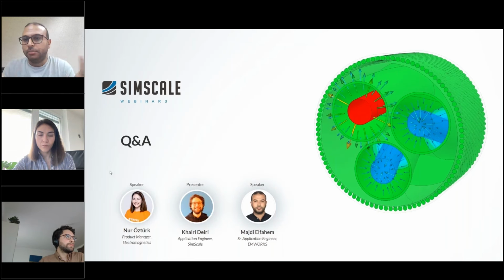You can model your PCB components and put some excitation, some voltage, and analyze the electric field distribution across your PCB and see what your electric field limits are, standards that you should not exceed at a certain distance from your PCB, and the software can help you to optimize and reduce the electric field radiation around your PCB circuit.